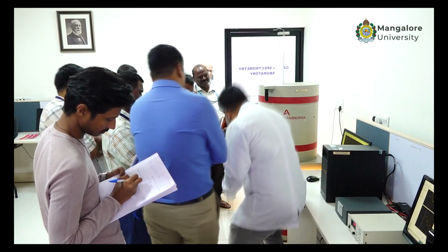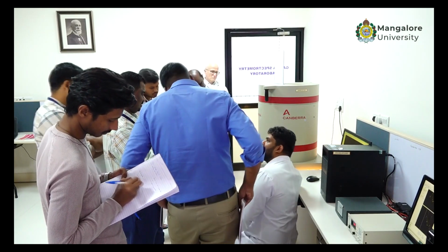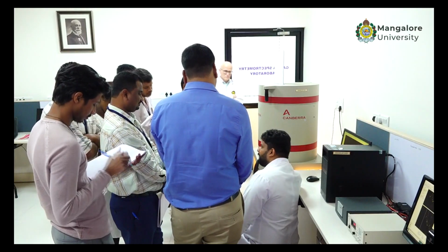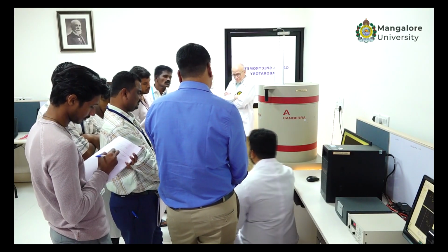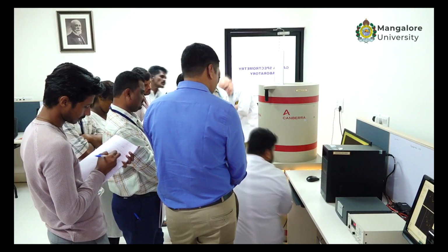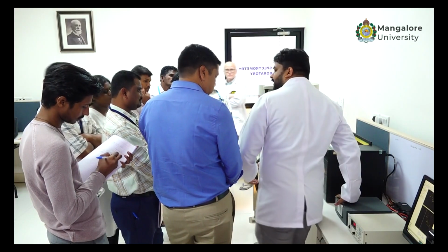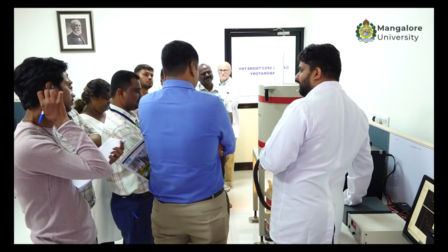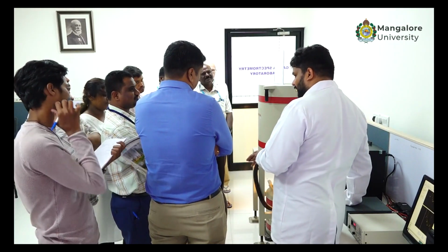So for that, we add a preamplifier embedded in the detector. Okay. So there is a preamplifier over there. That preamplifier amplifies the signal, and then that is transferred to this main amplifier. Okay. From there it goes to the multi-channel analyzer. So what is this multi-channel analyzer?